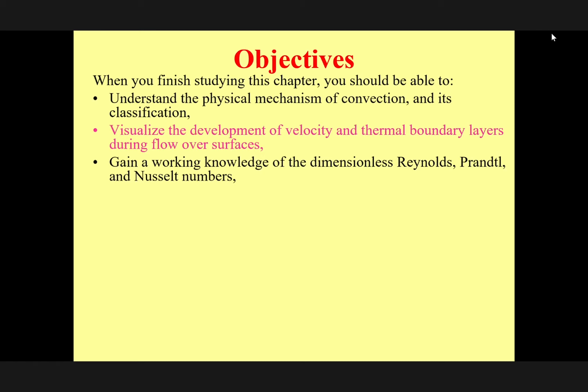Okay, the difference between the Nusselt number and the Biot number: with the Biot number, we were talking about the conduction inside the solid. And we also had the Prandtl number. Again, the Prandtl number shows the ratio of momentum motion to heat transfer motion. Therefore, now we are dealing with the fluid. There is a movement of the velocity, momentum, and also there is heat transfer.